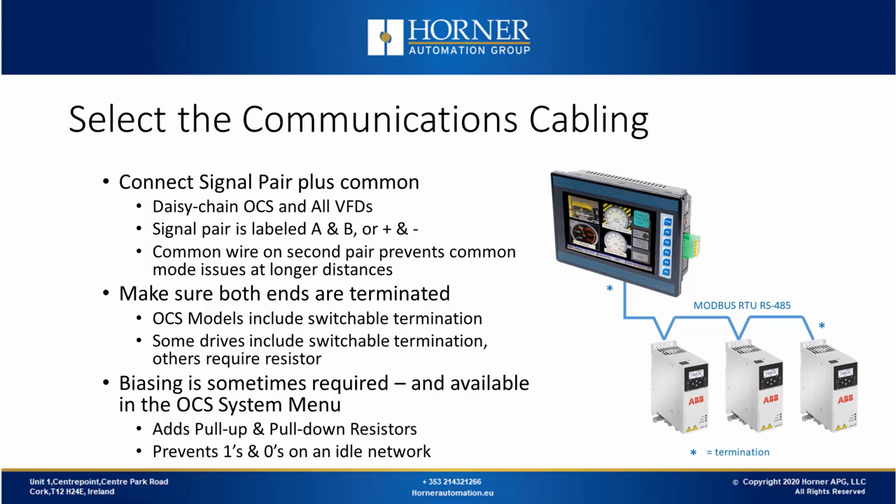You need to make sure, whether it's just 2 devices or 4, that the devices on the end of the network are correctly terminated. If the OCS is at one end of the network, then it has the ability for doing termination outside of the cable. So in the case of the XL7 that we're showing, and some other similar products, we have dip switches for setting termination. Some of our other models have a bit that you can set from the system menu, or from your application program, that turns the RS485 termination on and off.